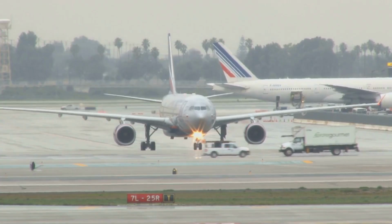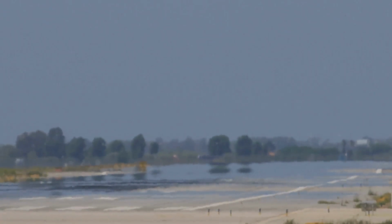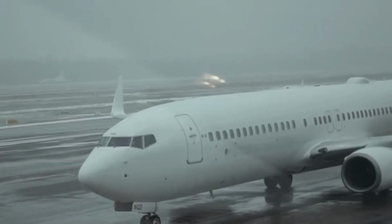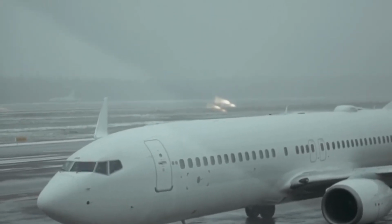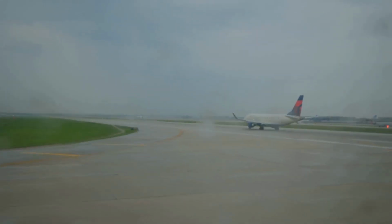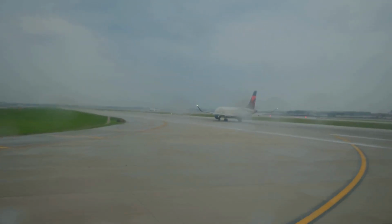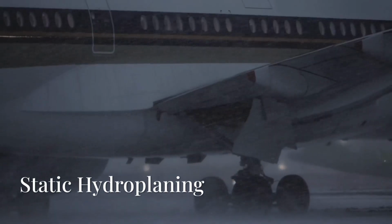Next is dynamic hydroplaning. This type occurs when the aircraft is moving at higher speeds, usually when there's more than 1/16 of an inch, about 1.5 millimeters, of standing water on the runway. Basically, the faster the aircraft goes, the higher the chance of hydroplaning.